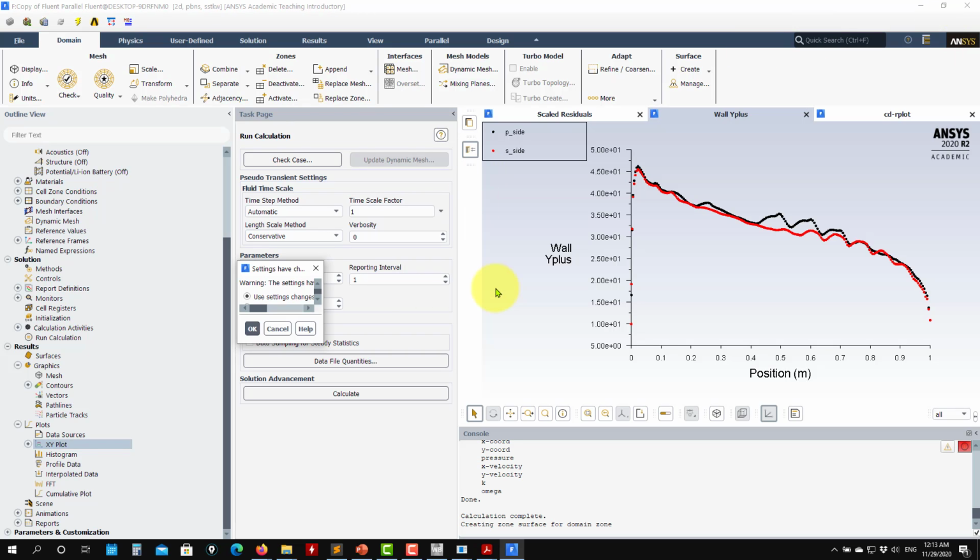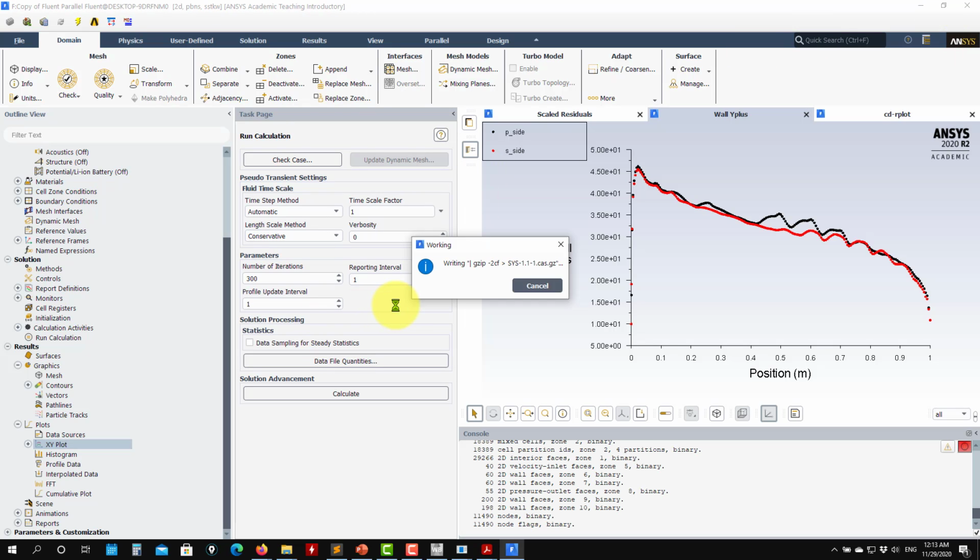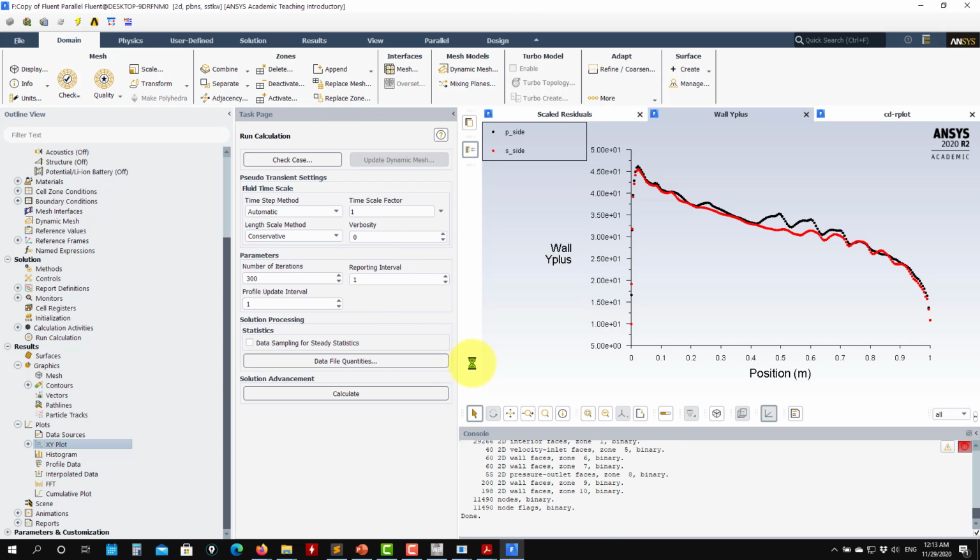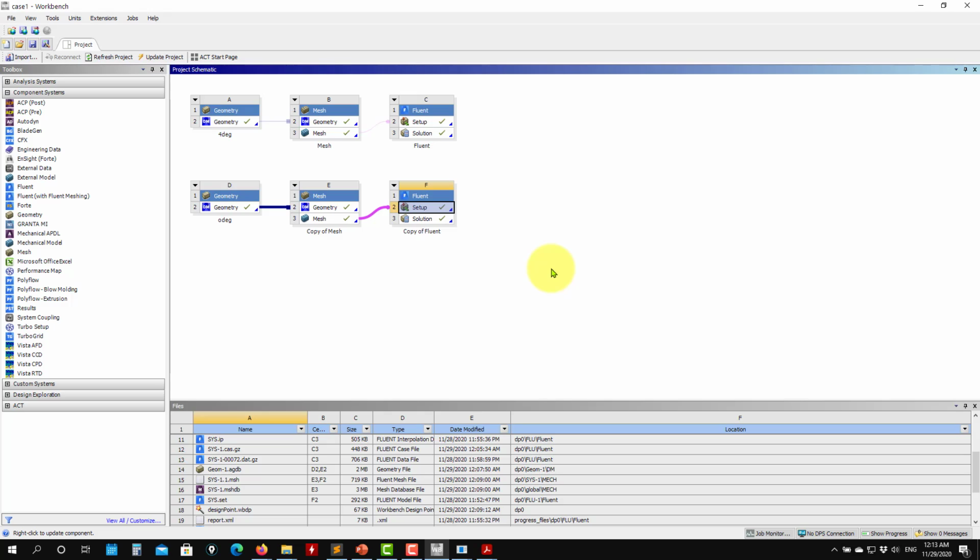So there is a lot of theory behind that. Now that you have that, you will run 3 cases. What you can do now is just clone this one and run, for instance, 10 degrees, so you can visualize the flow, if there is separation and everything. So this is your recipe. It is more complex than what I'm showing you, but this is enough to do the comparison for your assignment.